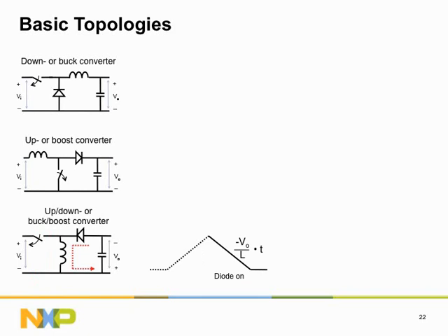In the secondary stroke, the current in the inductor keeps flowing, but it can only take the path indicated by the red arrow. Through the diode, the current charges the capacitor. Also during the secondary stroke, the voltage across the inductor is constant, namely minus VO, which causes the current to decrease linearly with time. This is shown in the waveform graph on the right-hand side.